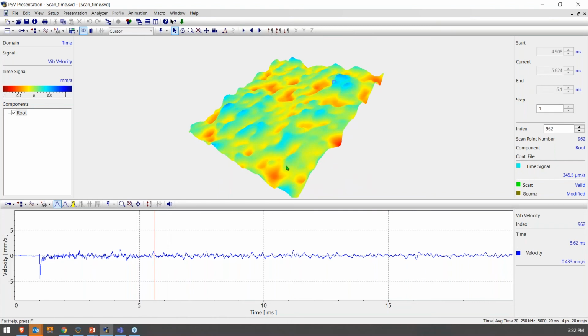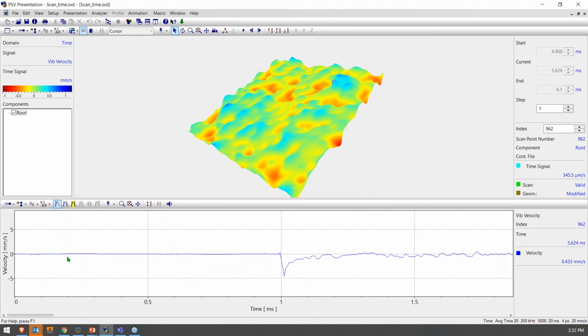So obviously there's a high ringing going on in this plate that can be visible, but it's important to understand this is not noise. Between measurements, we have to make sure we let the plate ring down so that we get to a point where the ringing is almost back to zero.